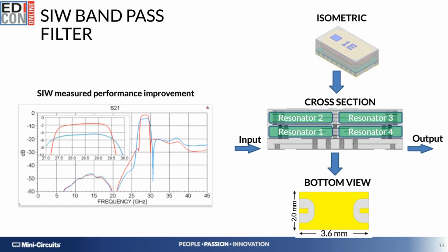We have also realized implementations of substrate integrated waveguide filters. What we're seeing today here at this slide are test measured results on two kinds of spins for the same actual topology. The blue plot shows the standard technological implementation on LTCC for this particular substrate integrated waveguide filter. We see very high mid-band insertion losses, with respect to a second spin on the same, employing the